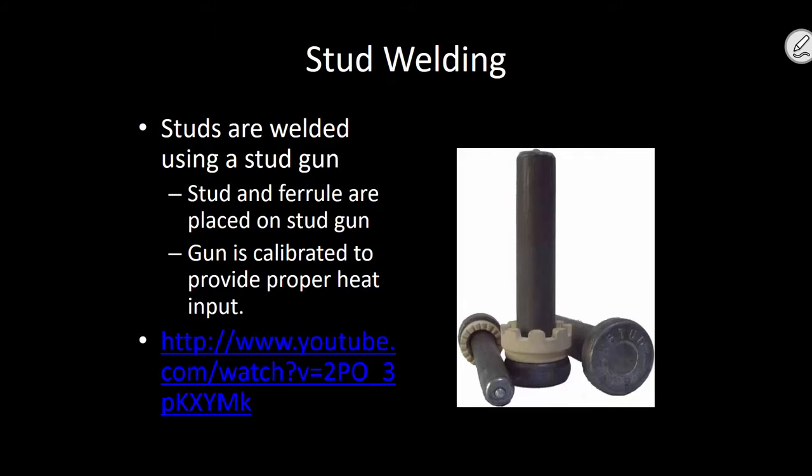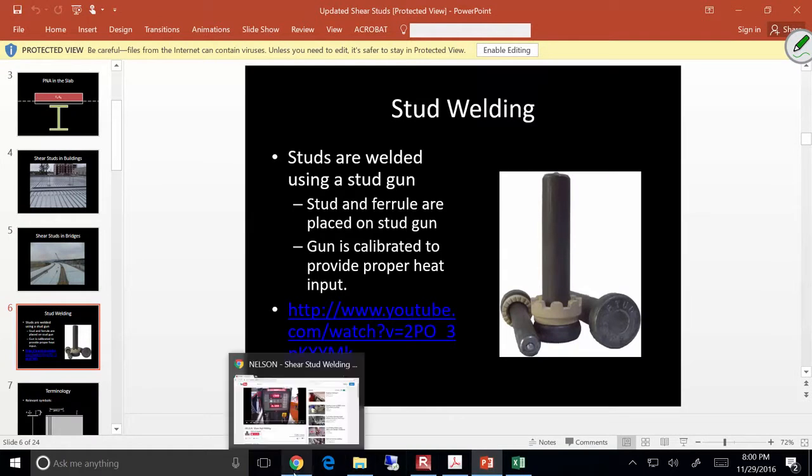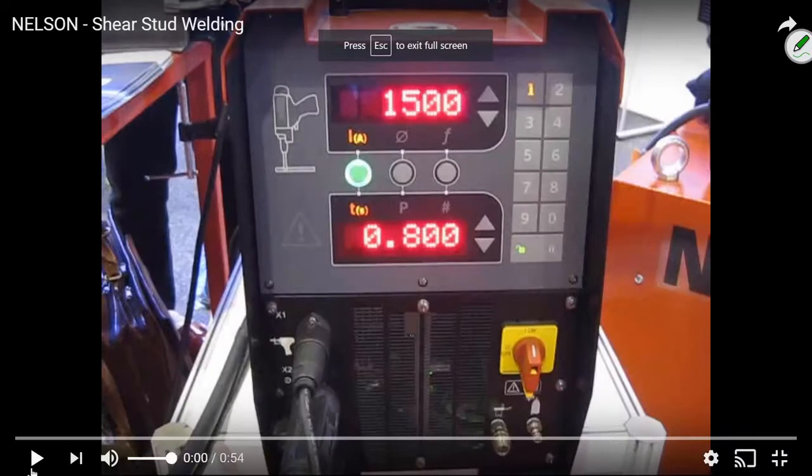So what happens is, here's the stud, it shoots the electricity, and it begins to melt the steel, okay? Then the electricity gets shut off, and as soon as it gets shut off, you have a nice little molten pool of steel, the stud gets shoved in. Steel cools down, melts together. Make sense? Now, I'm going to show you an installation, and I want you to follow along the actual stud, and I might replay it a couple of times to give you an idea.